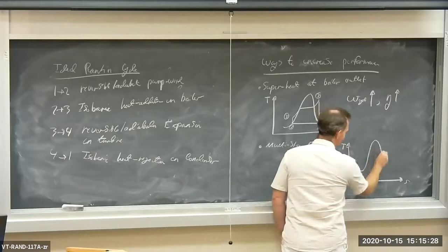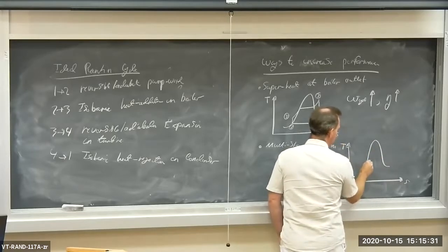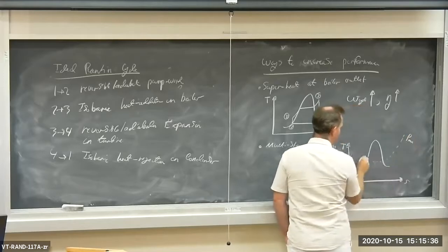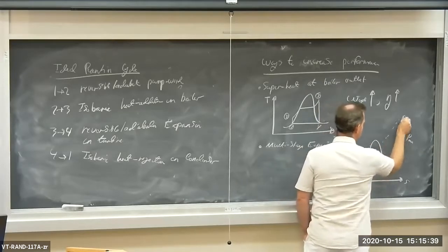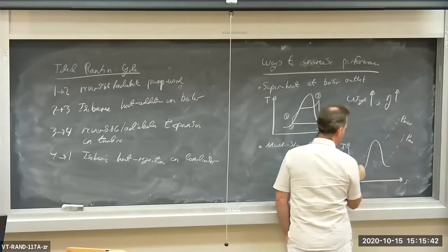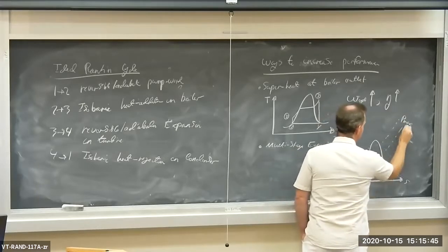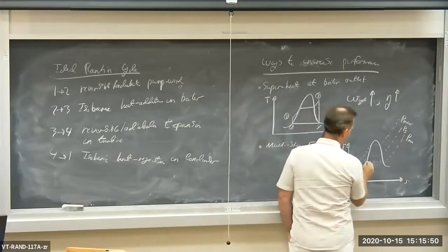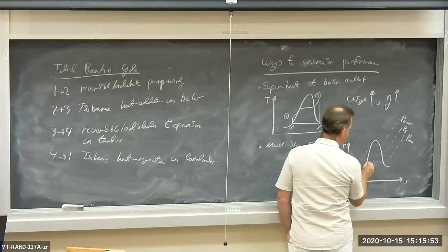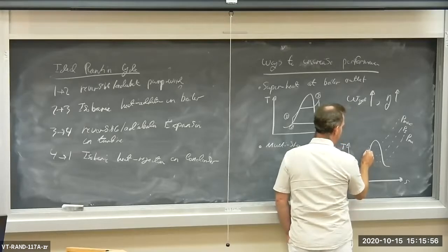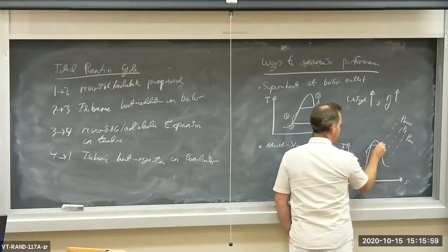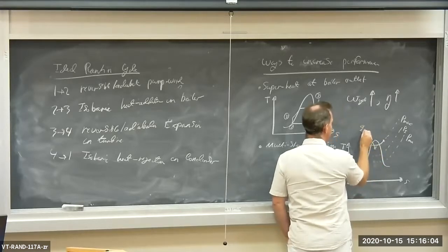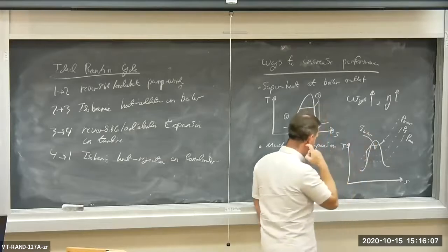So here's the saturation dome. Here's our P-min. Here's our P-max. And here is some intermediate pressure. So PI, I'll call it, some intermediate pressure. So what we can do here is we can start off with reversible pump work all the way up to P max, add heat, superheat. So here's where Q boiler is right here.